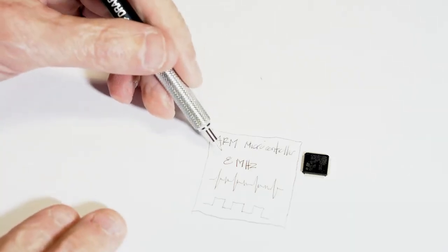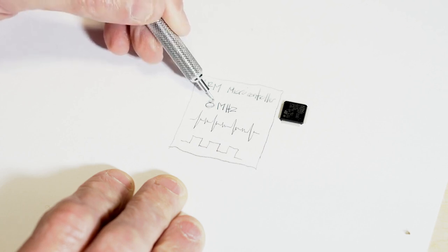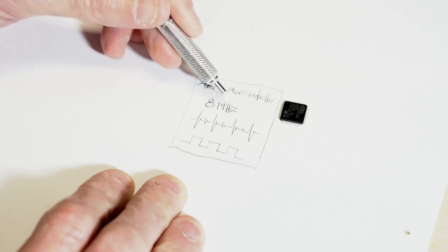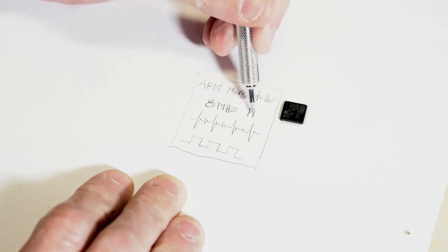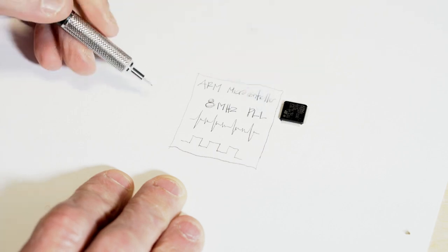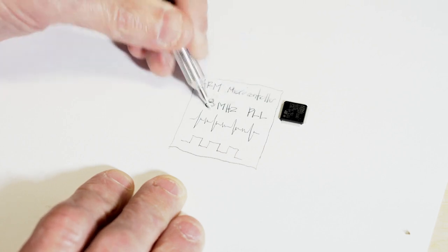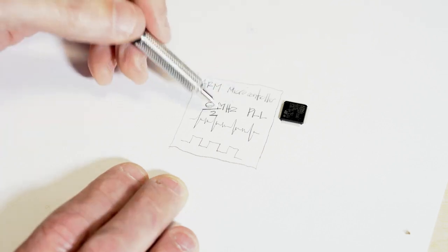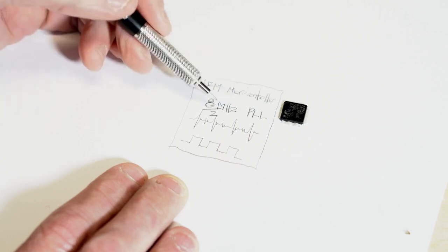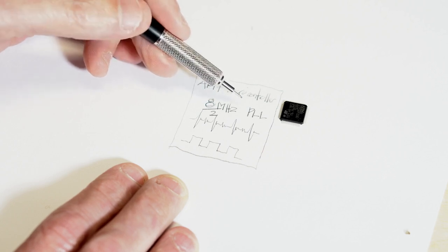So this is the internal oscillator, which is already available to you. The speed of this internal oscillator can be varied. You can pre-scale this, or divide it into a smaller speed, like maybe 4 MHz if you wanted to divide it by 2, or you can increase this speed using the PLL, which is a multiplier. All you need to know is that this PLL allows the internal clock, the HSI, to be multiplied. But it's multiplied by this speed divided by 2, which is 4 MHz. So let's go ahead and try this out and see what we can do with this internal HSI, and how we can make the clock speed faster using the PLL.